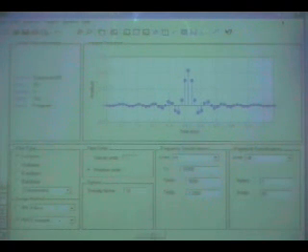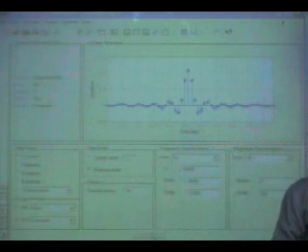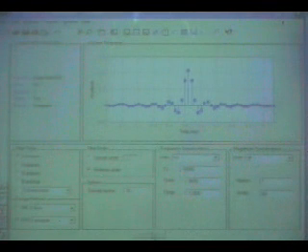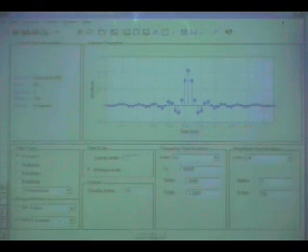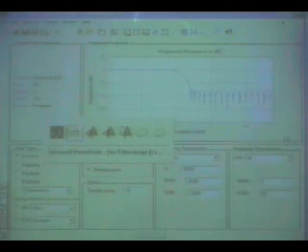And here, in half the amount of coefficients, almost half the size, you can design the same filter. So it's a very effective method. This Remez exchange algorithm is very, very effective, as you can see here. Though if you look at the frequency response, obviously there are ripples in the pass band and ripples in the stop band. But it'll give you a very good filter if you use the Remez exchange algorithm.